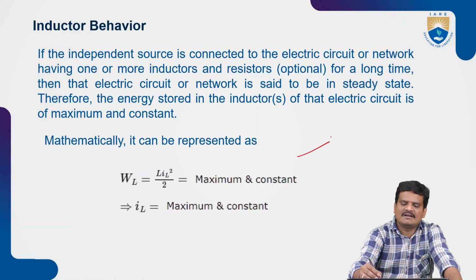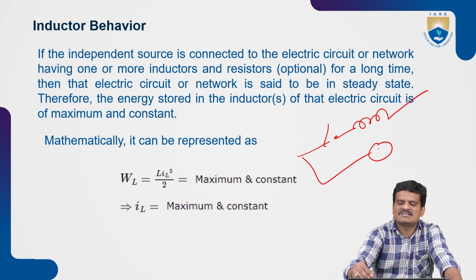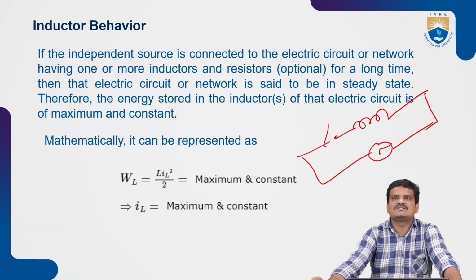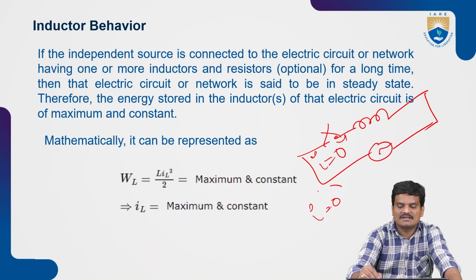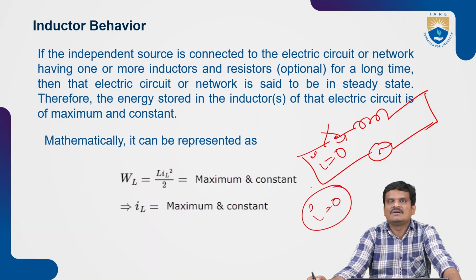Suppose I am taking an inductor like this, with a switching action, and some amount of voltage is given to this circuit. Before closing the switch, the current was 0, and after closing the switch, up to a certain period, the current is 0 in this circuit in case of an inductor because of its property.